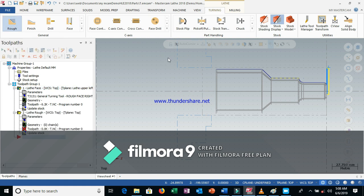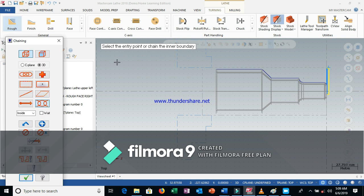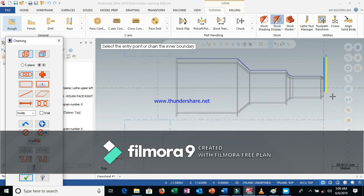Since we done the facing already, now you have to go for the rough. So in this rough cutting, first you have to select the boundary points with the chain. So how it has to cut, rough cutting. Okay, select the chain. So select the top line here. Okay, so top line, it will blink automatically. If it is feeling difficult, just make it zoom. Yeah, it's done. Now select the top line.